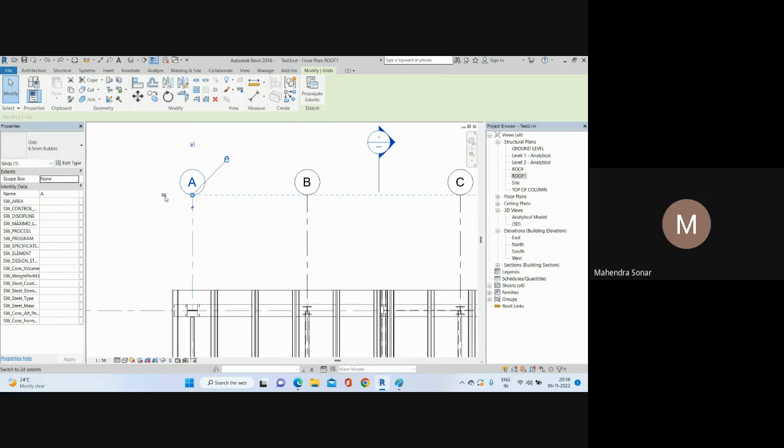If you set 3D and adjust this grid in this plan, it automatically affects all plans. If you adjust this grid line only here, as per this condition, you need to click here on 3D, so it converts into 2D. Then you can rearrange individually. Select, click here 2D, and then you can adjust.